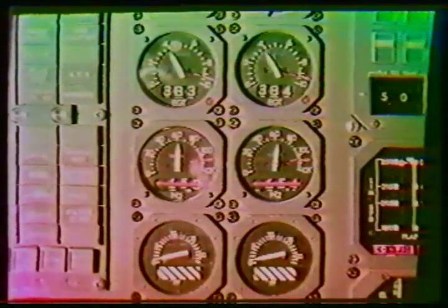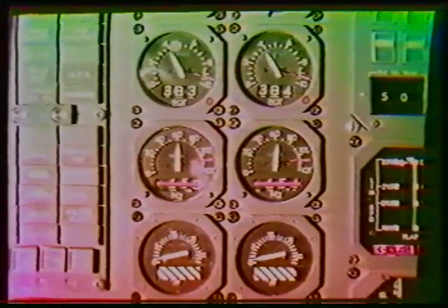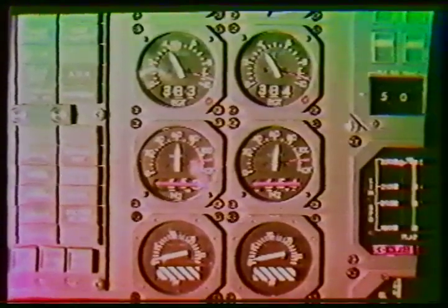On the center instrument panel, 4 indicators show the following engine parameters: fuel flow, N2, EGT, and N1. Each fuel flow indicator is fitted with a counter displaying digits of the same value as the pointer. In the event of an electrical failure, the pointer returns to 0, but the counter displays the last given value.